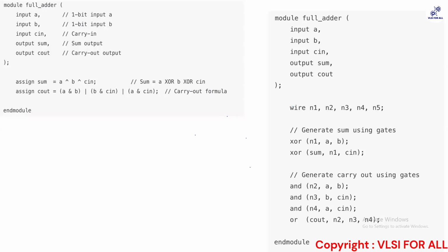For which kind of gates will the tool give high importance, ma'am, priority? See, the way it decides is based on your constraints. If you had a simple XOR gate, your design is simplified. But if you don't have an XOR gate, now the tool is doing it using NAND gates, so the number of NAND gates required will be larger. So the tool will do it on the basis of the constraints that you have provided.